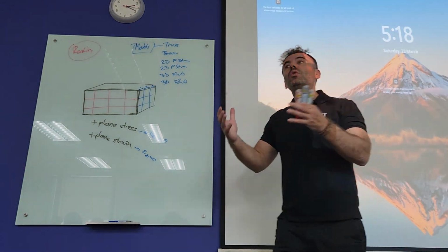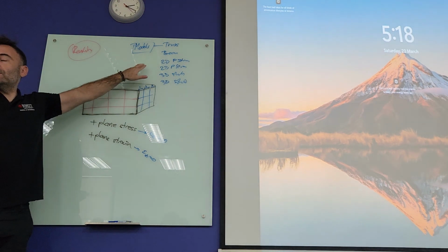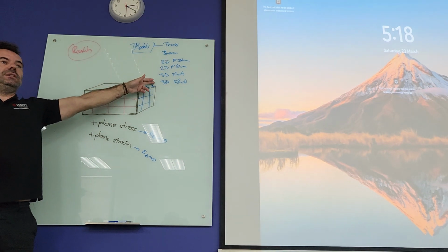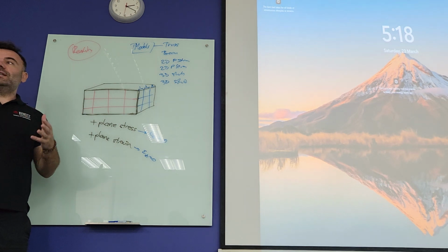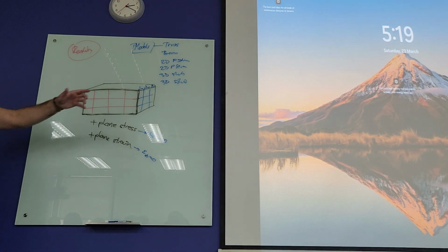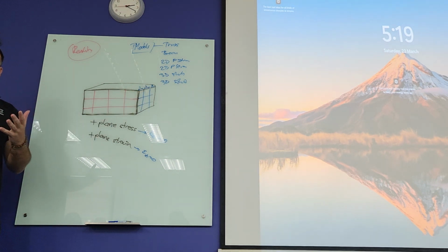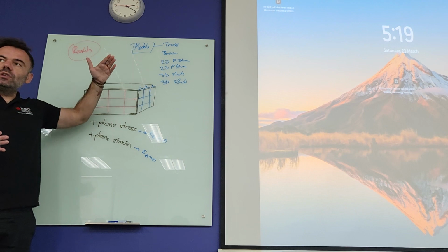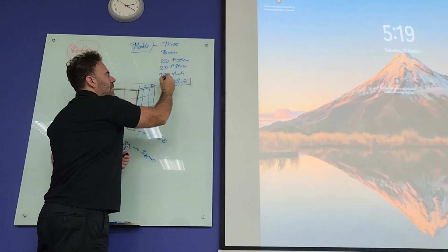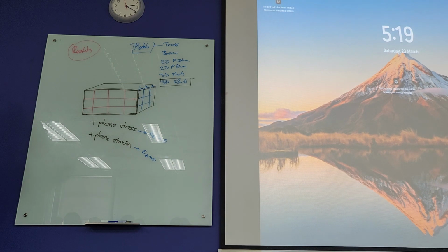So that's the whole point of this course, to understand what the limitations of each are. Remember we talked about trusses and we said they don't bend. So they are structural elements that don't bend. So if we have a structure in which we don't have bending, we can use truss elements to model it and be of good accuracy. If we can't, then we have to move to the next level, and so on. This one here, 3D solid, as I said, is the most expensive, but generally can be used for any problem.